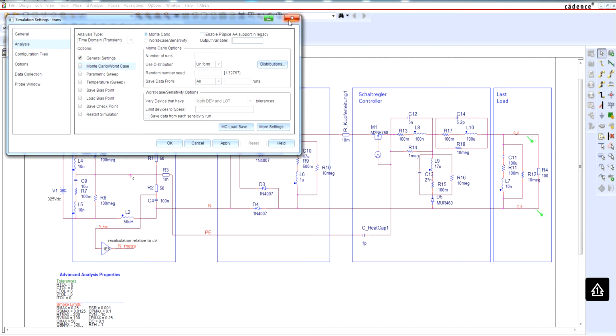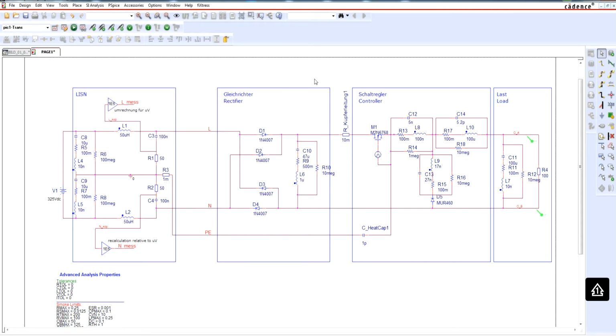But if I want to calculate for example the maximal value, or I want to calculate for example the rise time, etc., I'm not able to do it here in order to get statistical results. That's why what I'm going to use is PSpice Advanced Analysis for Monte Carlo.